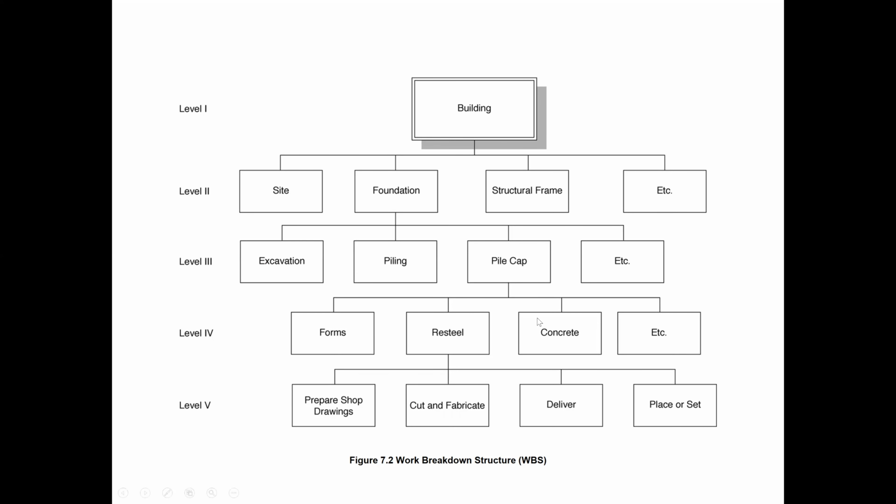Okay. So then the steel, they also prepare shop drawings. Okay, so how to cut those? We have to get approval of the shop drawing, cut those rebars per the bar bending schedule, and then fix those bars to make the steel net for this pile cap. Okay, so then place concrete or something.